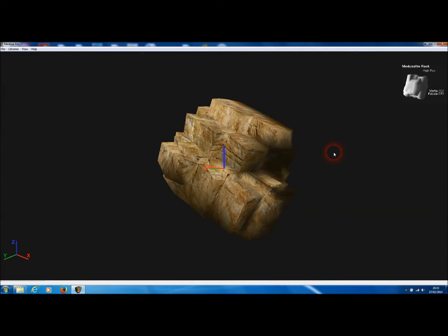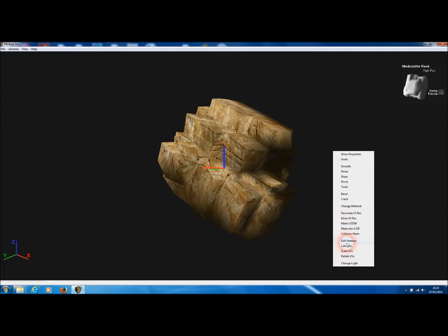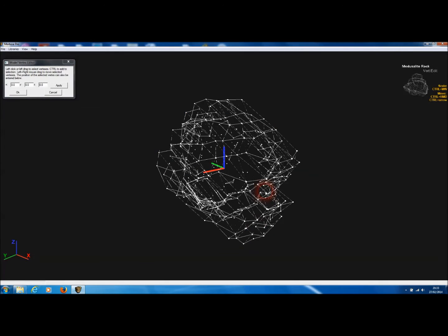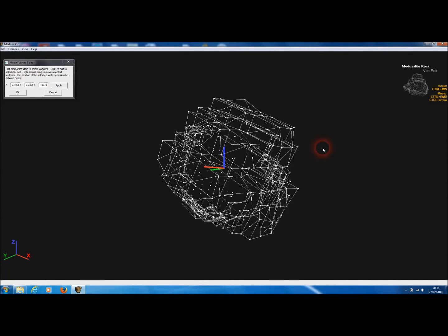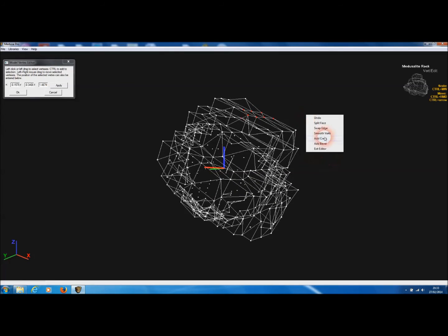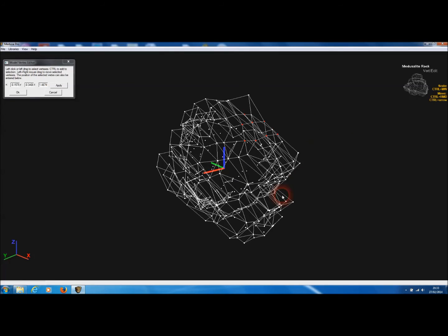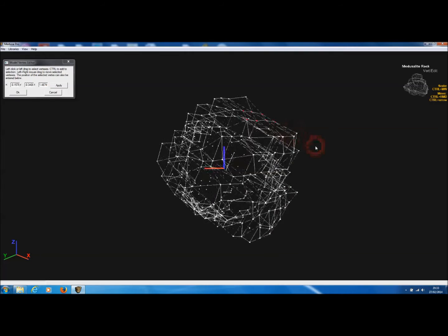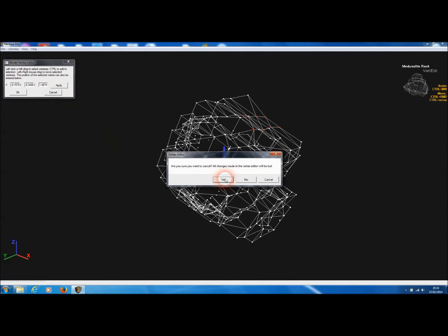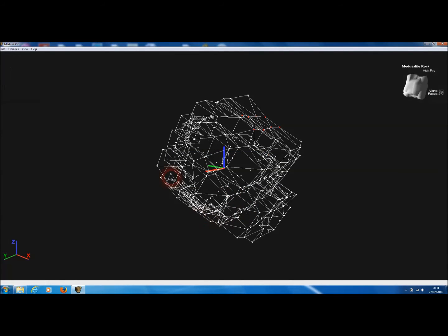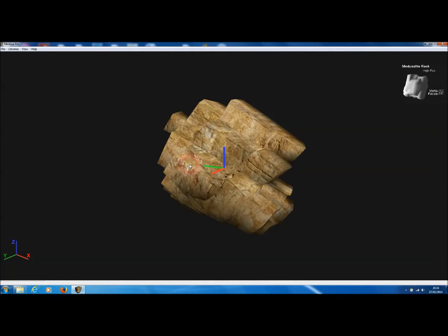As well as editing collision meshes, we can also edit the vertices on the high resolution model, and we can move around individual vertices, or for example we could select a whole bunch of vertices and do smoothing just on those vertices. So there's a per vertex editor also in Medusa Pro. Let's come out of there.